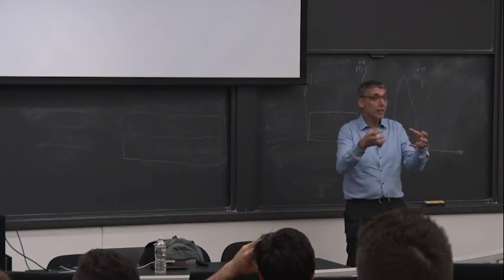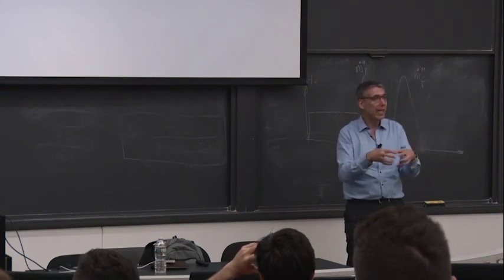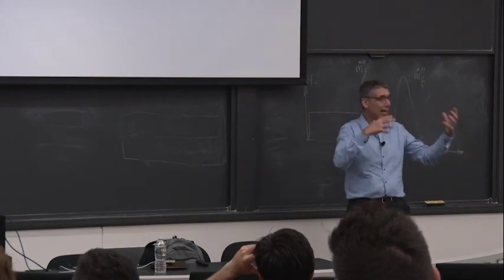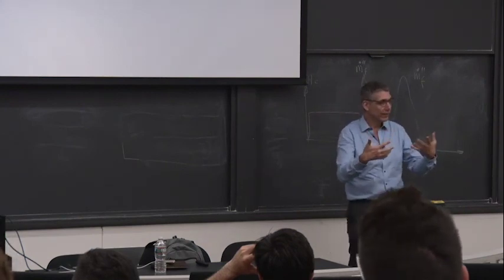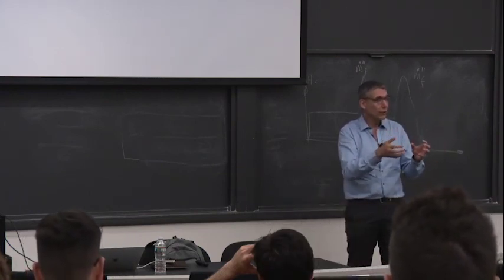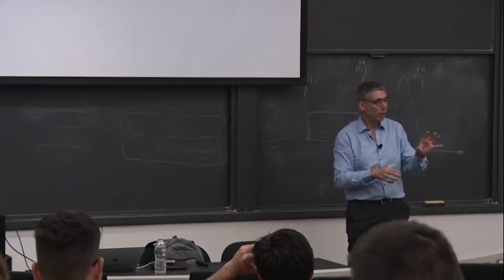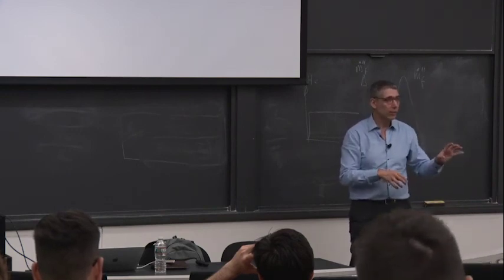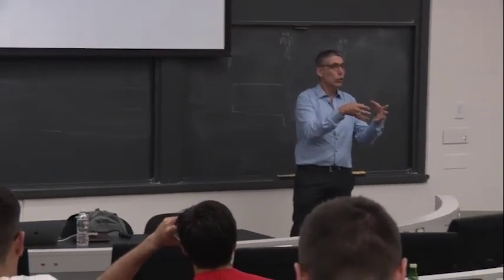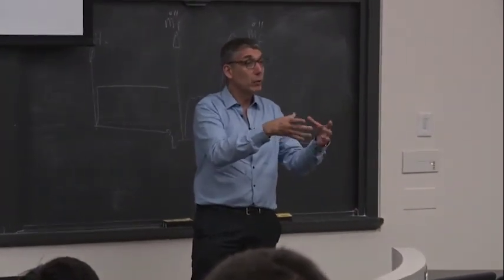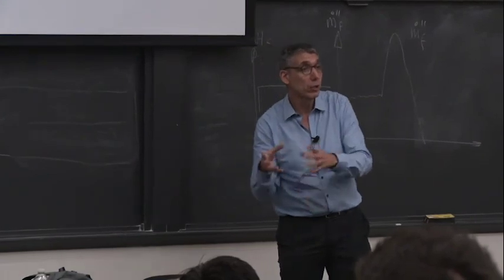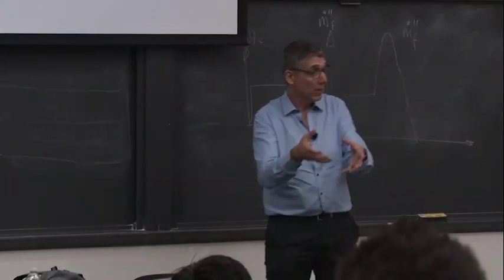But this alpha that we had assumed as being just simply a number that brings certain material properties, when you break it down, you realize that it's a combination of the material and environmental properties. And there is a very clear physics that tells you which are the parameters that dominate the problem, which ones are related to the materials, and which ones I'm introducing that are part of the environment. So if I want to use those properties and the conditions are different to the test, I have to make corrections. Because the heat transfer coefficient is not going to be 45, it's going to be something different.